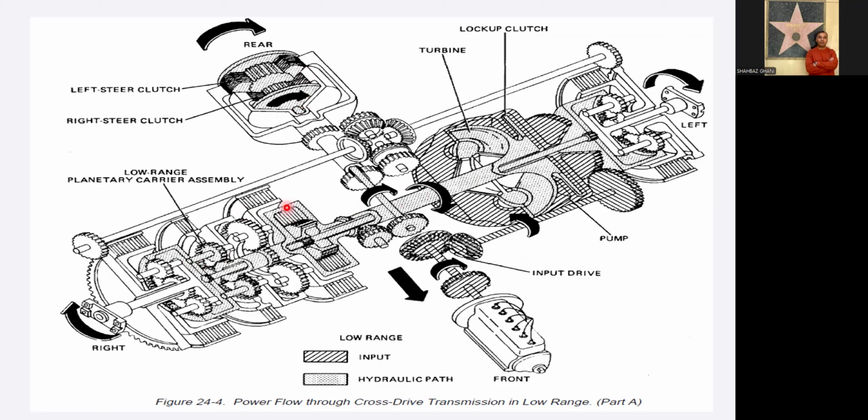This is the automatic transmission, or planetary gear system, for the gearbox, and this is for your steering clutch, if you have to steer left and right. The beauty of this transmission is that it does a pivot turn, not a skid turn. It turns 180 degrees at the very same location.